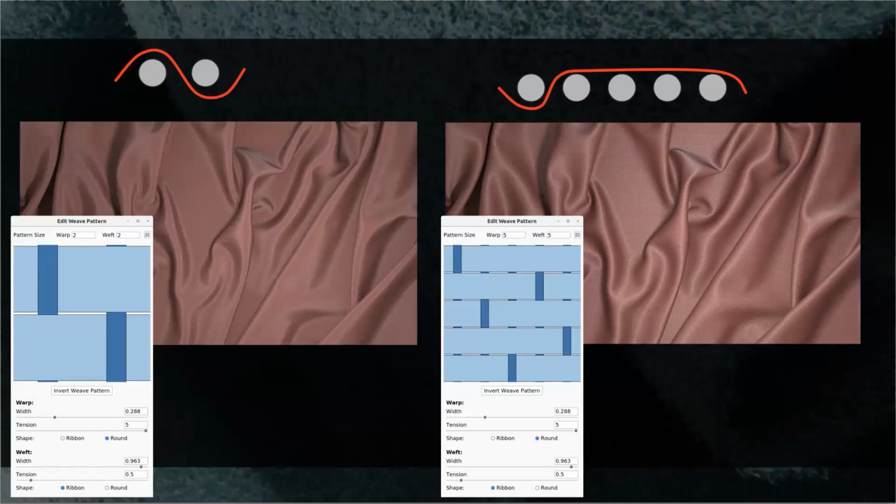But the key ingredient that we're missing is actually how do the yarns actually look in 3D? Because some types of weaving patterns have a very tight weave pattern where the yarns are stretched tightly, and some have weaving patterns where they're less tightly wound. So we developed a very simple physics-based model for how to compute this. And that's what you actually do when you enter the edit weave pattern. It does a small physics simulation of how would these yarn look and lie in full 3D if you were to pull them at this strength. So that's what the tension means.